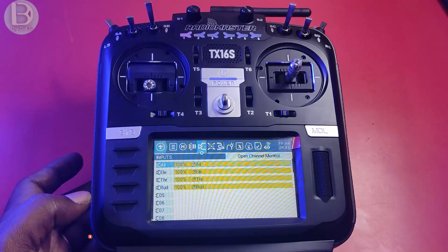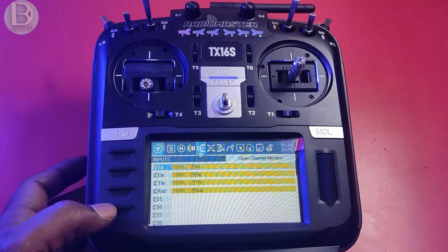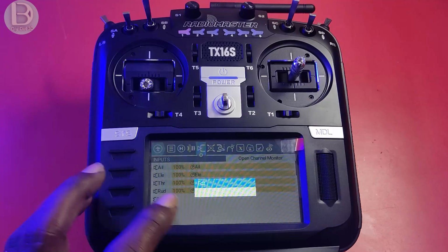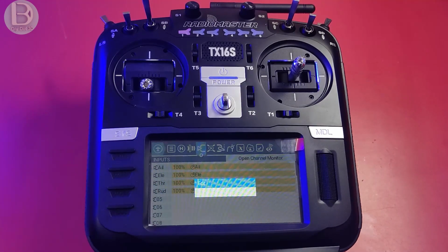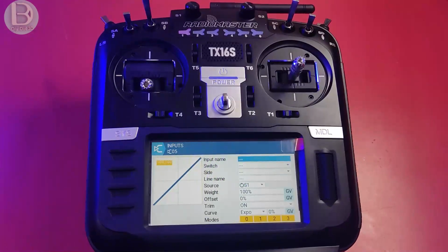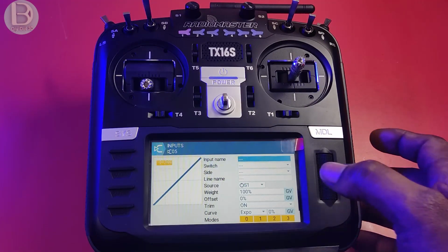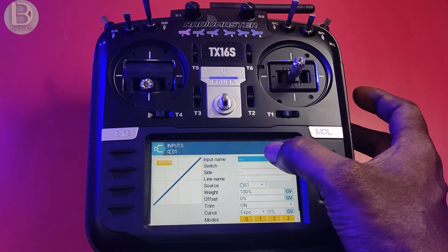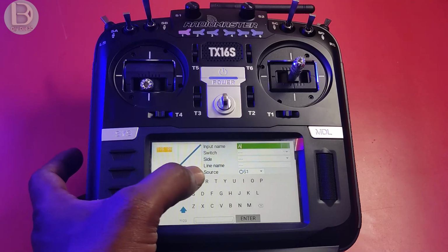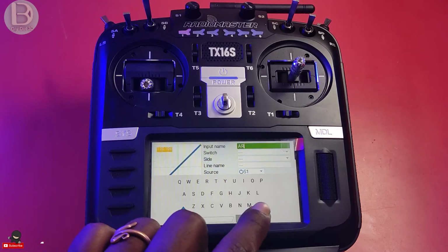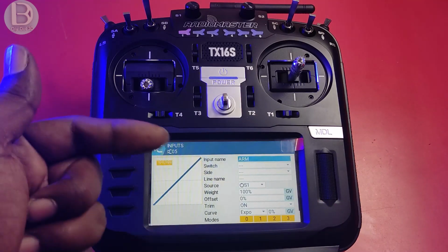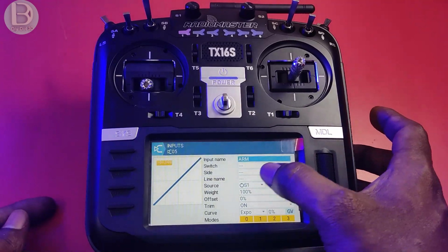I'm zooming a little bit so you can see a little better. I'll press this number 5 channel. Click on this edit. Here, input name, you can give some name. I want to use this channel for arming, so I will give ARM, just enter.